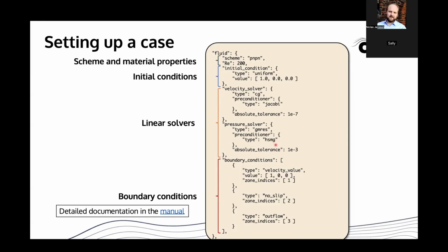You can create another sub-block related to the coarse grid solver in this multigrid to set a lot of options. So these files can become quite large, but we have tried to set the default values as sane as possible, and the more fine-tuning is left for the more advanced users, or when we have to debug cases that are not working.